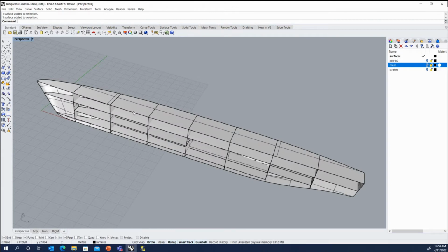Where we get some differences there are when you're dealing with the hull, the shell plating, where the flare in the hull can change the girth from the vertical sides at midships to something with a significant amount of flare up at the bow. You might have 30 degrees of flare up there, and that's going to greatly affect the length of that section going from the second deck to the main deck.